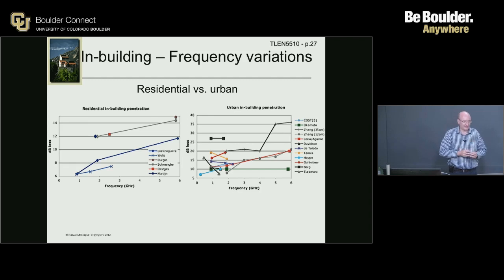And that's a general aspect, yes. The higher the frequency, the smaller the wavelength, the more it's attenuated by little devices, particles, obstacles, scattering, etc., that waste power. So these are mostly median values, and you see that they're fairly reasonable below 1 gigahertz, but start to be pretty high after 2 gigahertz.